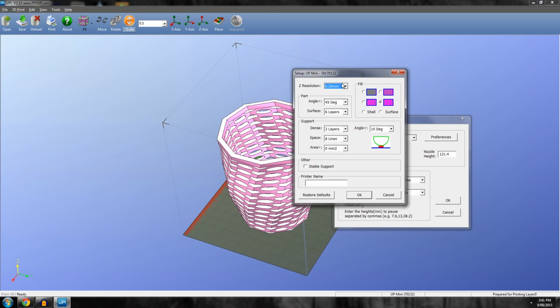0.2, to be honest, 0.2 at a fine setting on a nice high polygon 3D print looks amazing. Like the actual quality you get out of the print will look really good. I rarely have to go any lower than 0.2 on any machine, let alone the Up Mini. 0.3 is really fast and probably a bit too low resolution. 0.25 is a good medium setting, I would say.